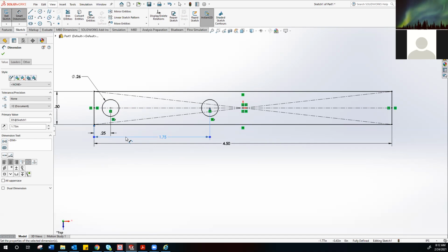All right. So what you've got to look at here is you tied it down. So this string right here is a tie down. But that won't do it. So see this little tangent buggy you got here? When you drew it, you made a tangent to this line. So take that and leave that one. Oh, look, it's what we did. Sometimes you get constraints you don't want.